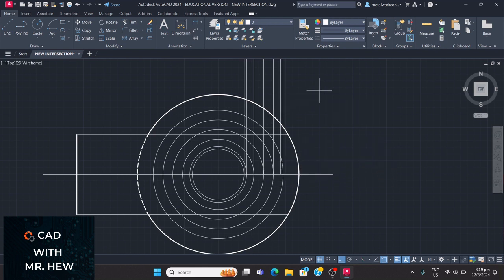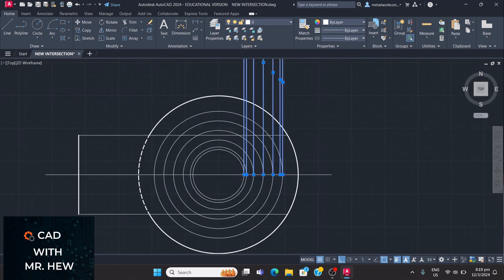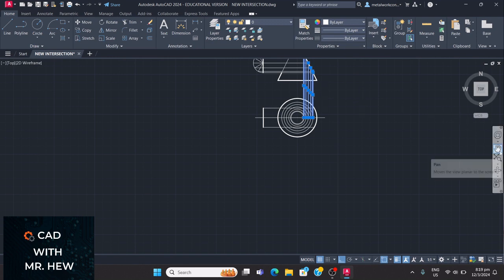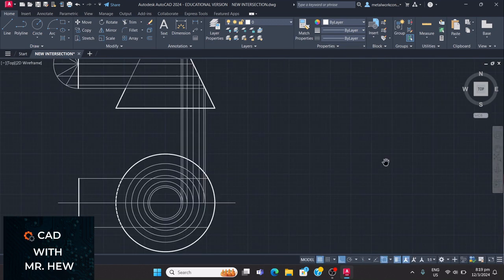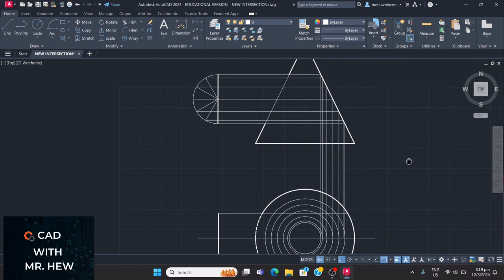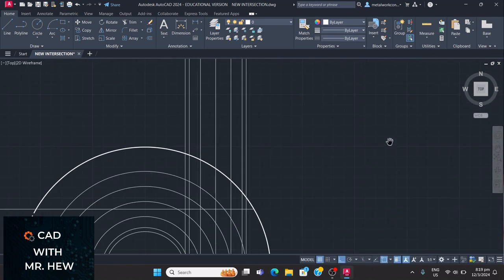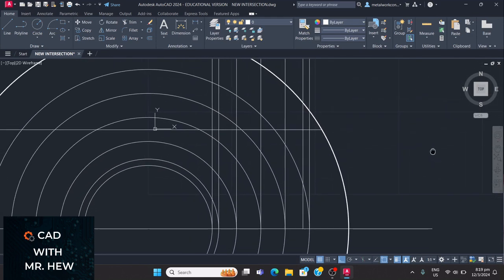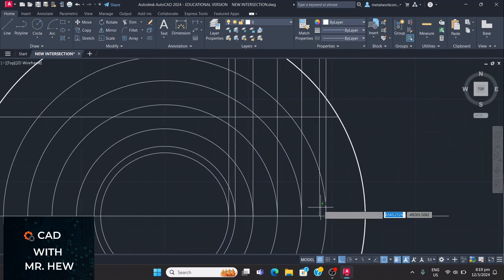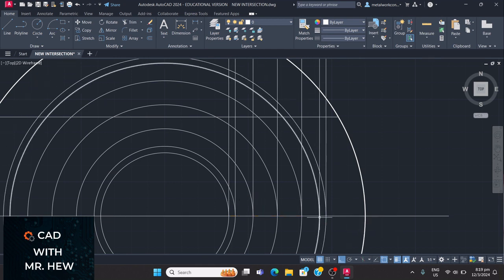These lines coming down are the lines that we use to get the radius. So okay, remember it's coming down from the top. Let me show you. See? It's coming down from the top here. So we're just doing the same procedure, all right? So we blow it up a little bit so you can see, right? So coming down, this will be the last one, this one, this one, all right? So we go center, radius, right there, see? Enter.